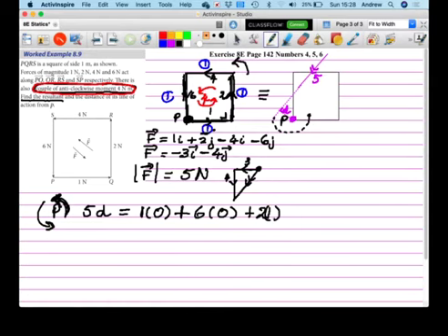And now I'm on to my last force, which is 4. And again, if P is pinned, it's going to have a turning effect going this way. And it's going to have a perpendicular distance of 1 from P. So it's going to be plus 4 times its perpendicularness of 1.